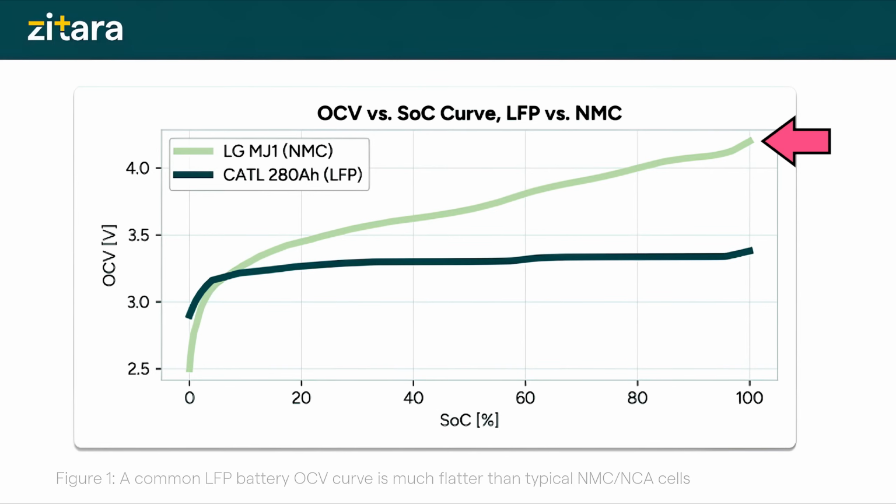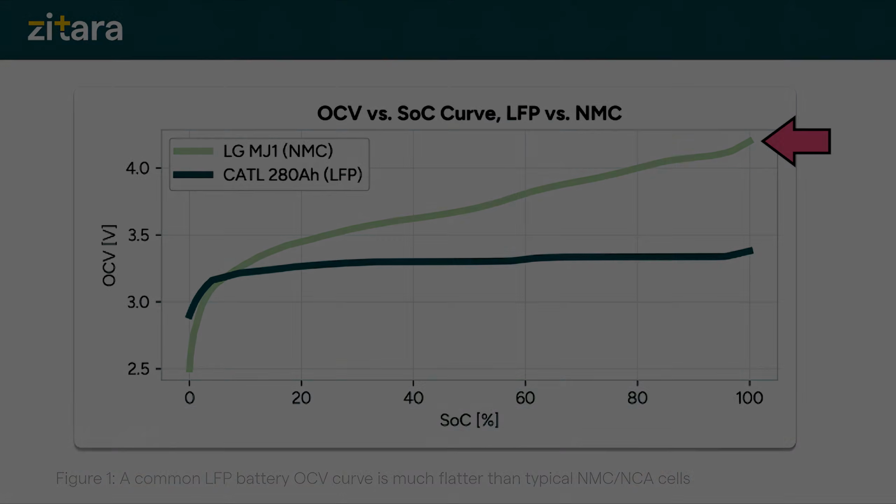Yeah, absolutely. So your power converter is going to have to be a little bit more carefully designed for a wider voltage range in a chemistry that has a wider voltage range. And actually, going slightly off piece from this discussion, a good example of a challenging chemistry there is sodium ion, because there's quite a wide voltage range. Another good example is a supercapacitor, because if you really want to extract all the energy from a supercapacitor, you have to go down to 0 volts.